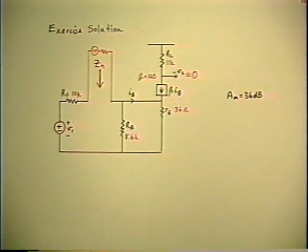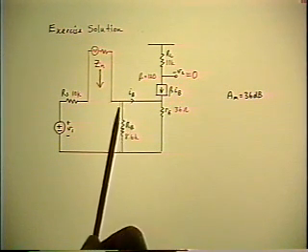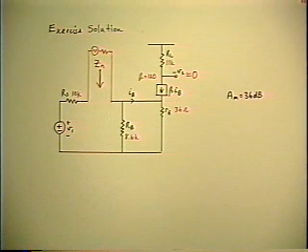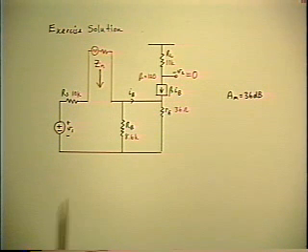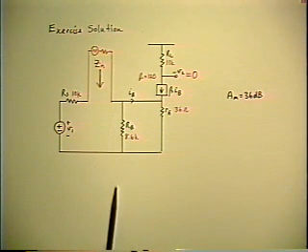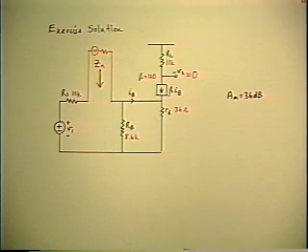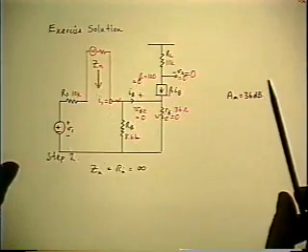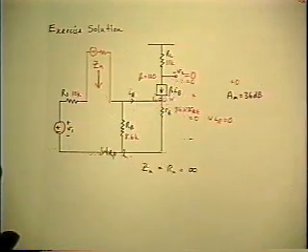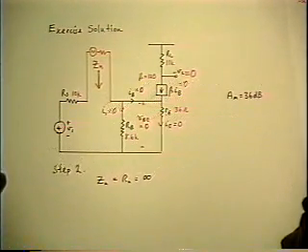So no current in RB either. So no current in the second source. So regardless of its voltage, 0 current is drawn from it, and the Rn is infinite. Now, you're going to tell me you knew that, but you didn't believe it.